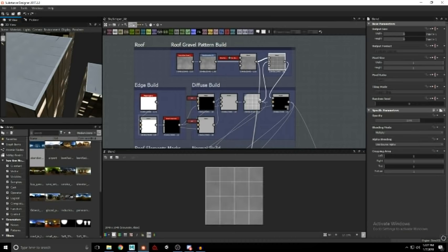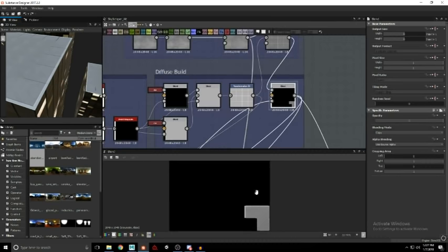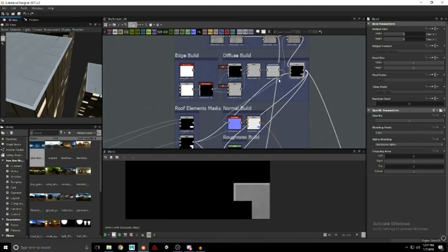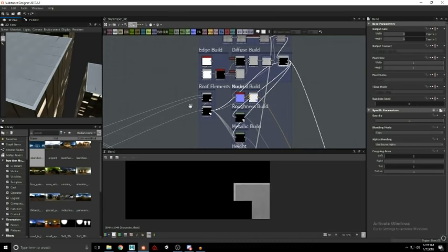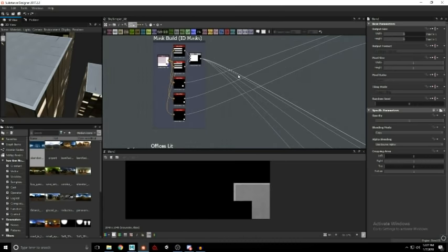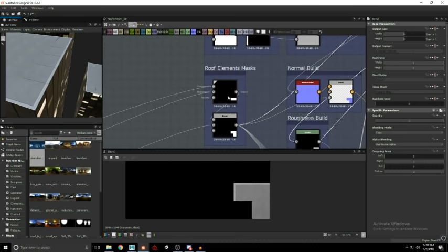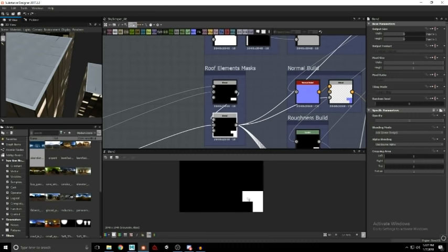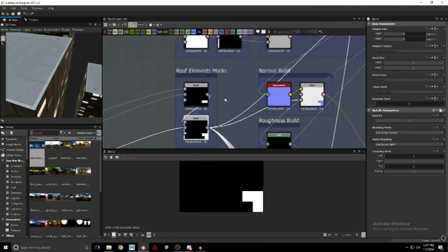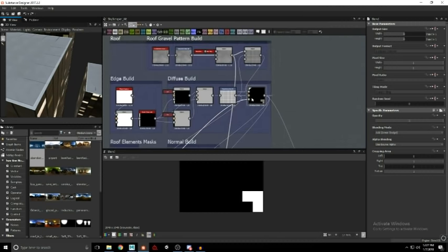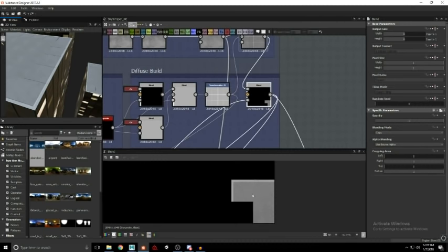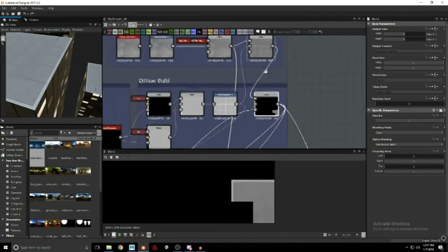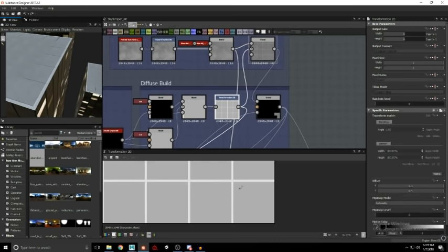All right, so up here we're going to blend those together, and then here we're going to take what we want out of this. And what we want is over here, these are our rooftop blend nodes, and these are coming from our mask. So what we're doing is we're combining these. These first two, we combine them together, then we're going to combine it with our third, so we get just that threesome all together there. And that we're going to bring up here and say, you know what? I want to take this that we've already created, and I want to blend, and I want to cut out just that area. So what we're doing here is, this is our shape with our colors.